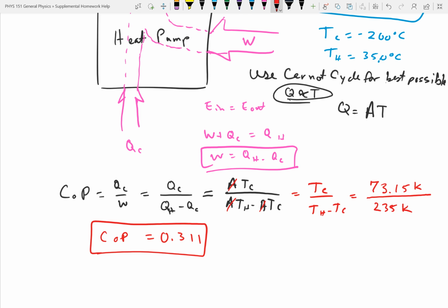So in a place like Nebraska where it gets hot in the summertime, you want an air conditioner that works well for a big temperature difference because here we have like 95, 100 is the highest it gets. So the difference in temperature is a little over 20 degrees. Not horrible. If you go to Arizona, it might be 120 out. Now you're talking 40 degrees. You really need a good air conditioner there. Or, as we learned in class, because it has a low humidity in Arizona, you can use a swamp cooler. Let evaporation do its thing.